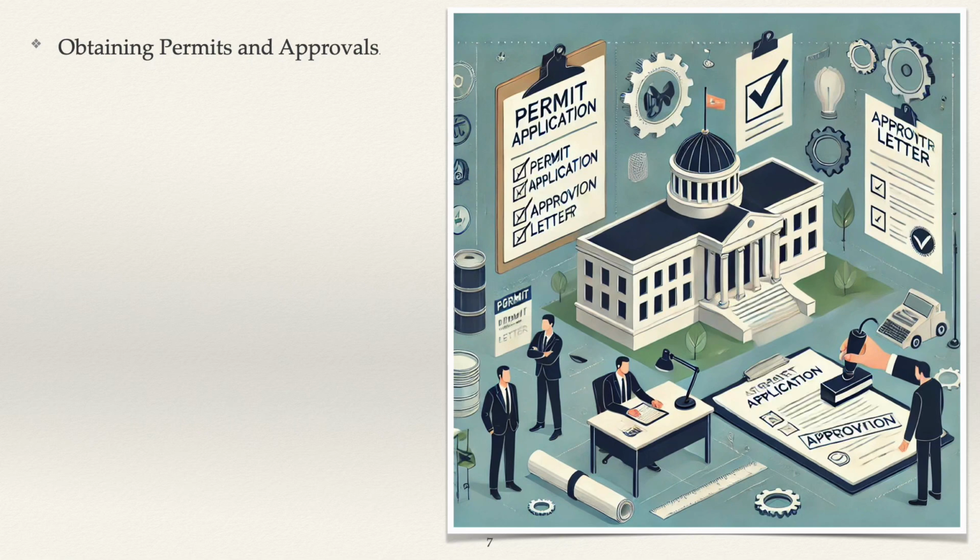E. Water usage. Permission must be obtained for using river water for construction activities. Similarly, if government potable water is to be used for purposes such as concreting or other construction needs, prior approval must be secured from the relevant authorities. F. Soil usage. Permission must be obtained in advance from environmental and other relevant authorities for using soil in activities such as filling and road construction.